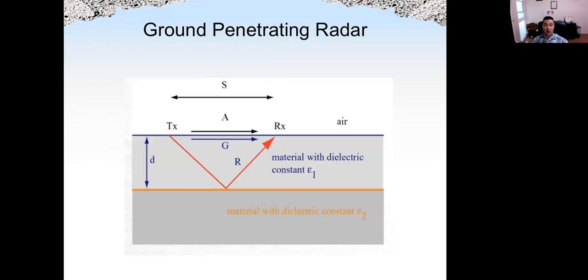Here shows how GPR works. The instruments include the transmitter, which is TX here, and also the receiver. Sometimes the transmitter and the receiver are in the same unit, and it can move along the surface of concrete with a wheel. The GPR does not necessarily need to touch the concrete surface, which means you can remotely sense inside the concrete with a certain distance between the concrete surface and the instrument.